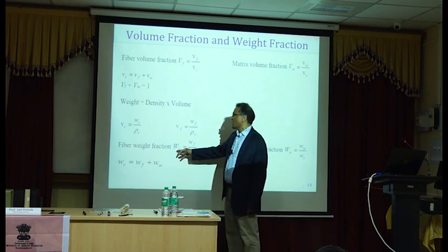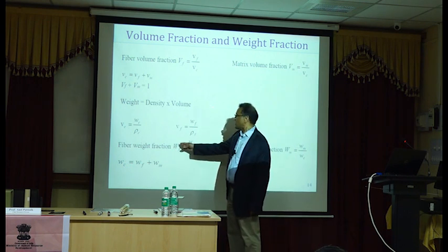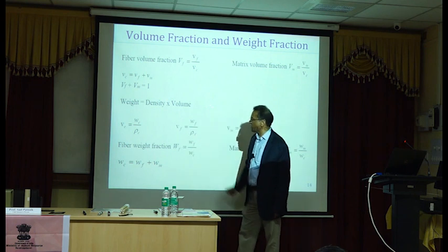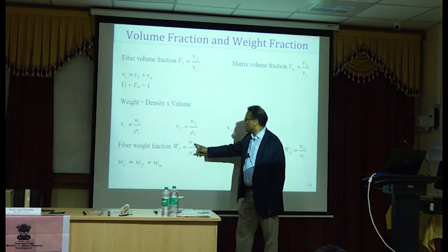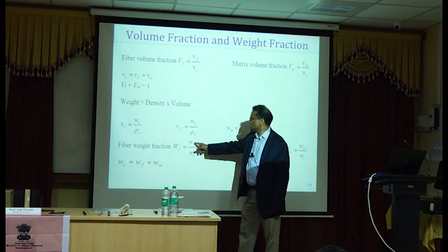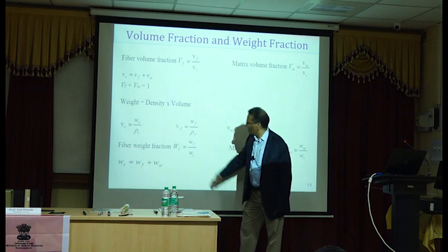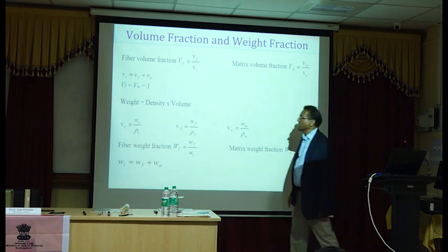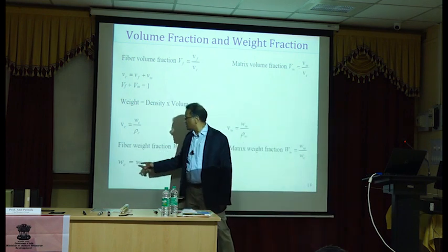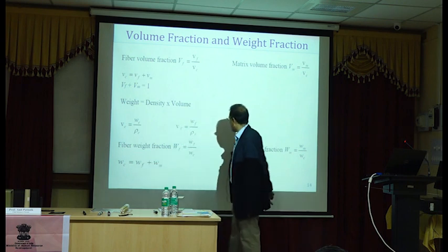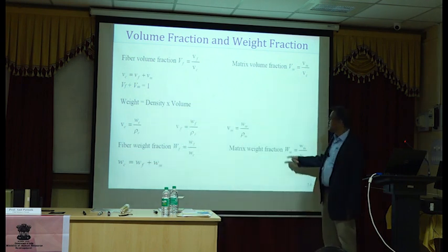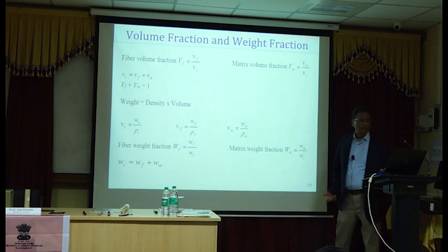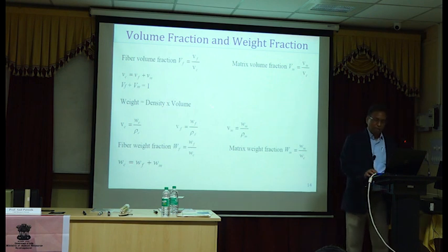So fiber weight fraction is W, uppercase, which is capital letter, Wf equals lowercase, which is small w subscript f over w subscript c. So once again, wc equals wf plus wm. Okay, so of course matrix weight fraction is Wm.